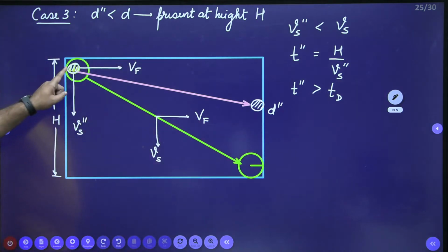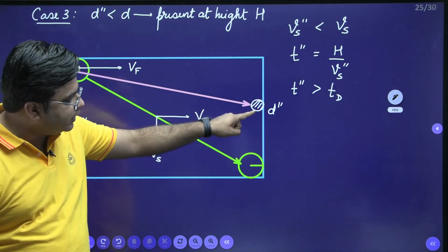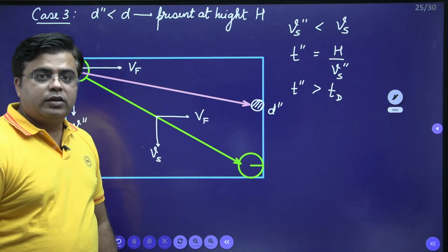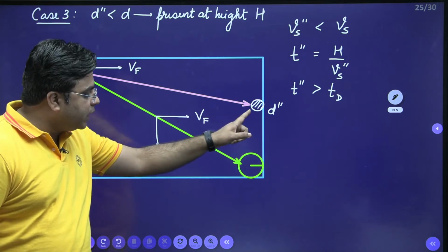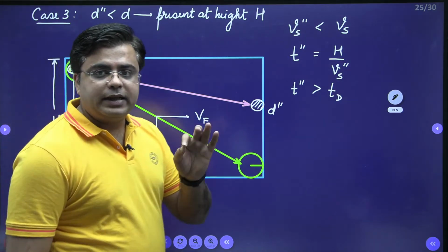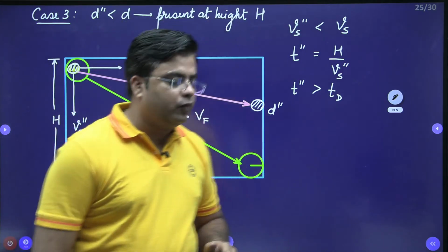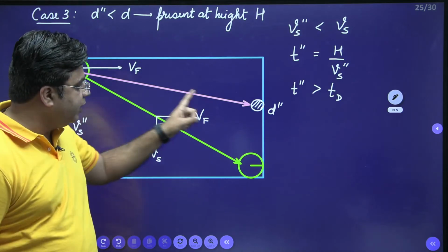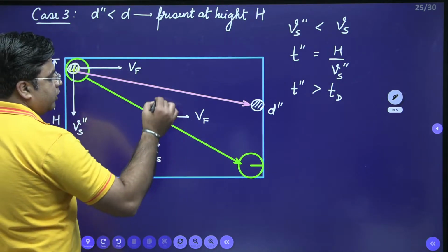You can clearly observe that this smaller size of particle hasn't reached the bottom of the settling zone. Therefore, these particles are not considered to be removed. A particle is only considered to be removed if it reaches the bottom of the settling zone. This particle hasn't reached the bottom of the settling zone.